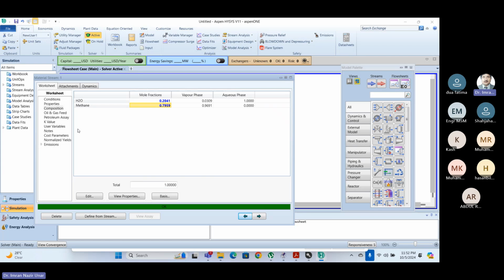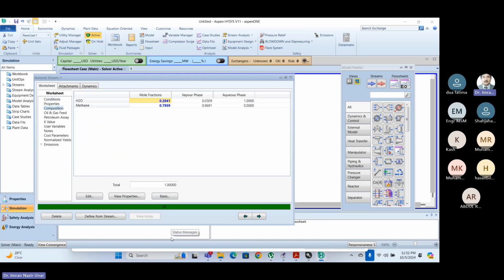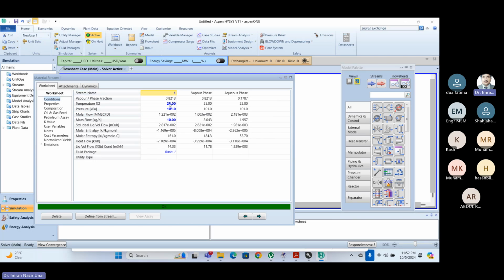This is very important sometimes in the oil and gas sector, because Kashif Saab and I were in SNGPL, and this was very important for gas measurement, where our GC calculates how much C6 plus component there is, and then makes the overall calculation 100%. Anyway, now you see that when I have given the composition and these three conditions, the stream is converged.